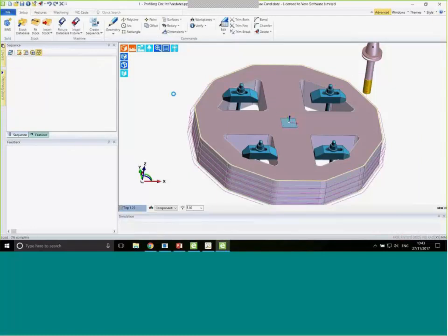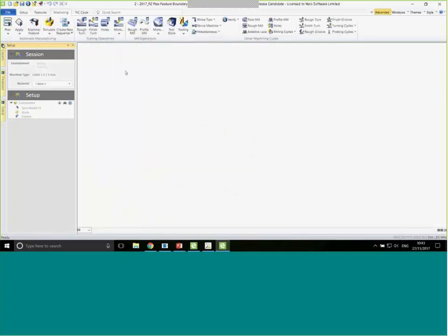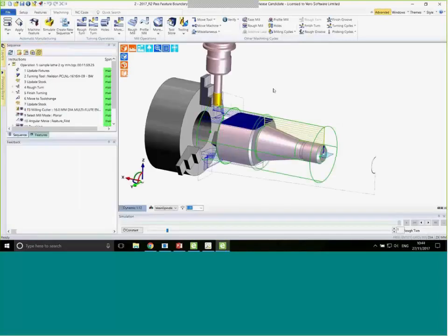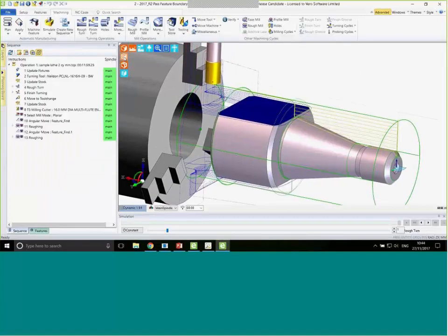So moving on, the other item I would like to speak about was to do with the boundary. So boundary control, as we know, clips back or chaperones back the toolpath. And in this particular example, what we'd like to see is the toolpath being a little bit more accurate, a little bit more efficient. And in fact, can't really blame the toolpath because it's perfect. We are saying to the toolpath, use the stock. So here is the stock. So it's done this correctly.